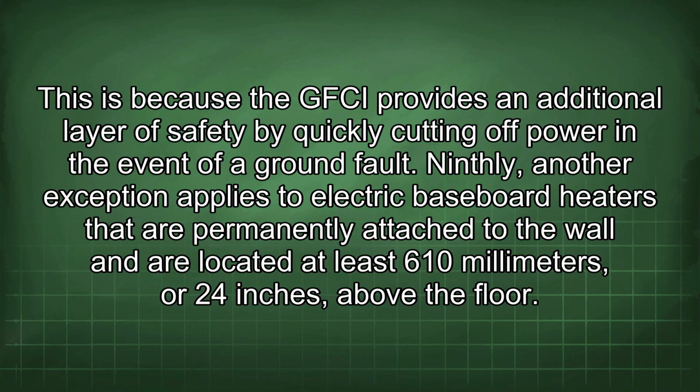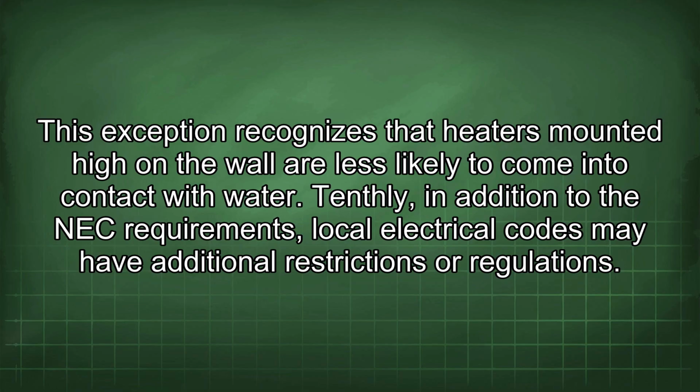Ninthly, another exception applies to electric baseboard heaters that are permanently attached to the wall and are located at least 610 mm or 24 inches above the floor. This exception recognizes that heaters mounted higher in the wall are less likely to come into contact with water.